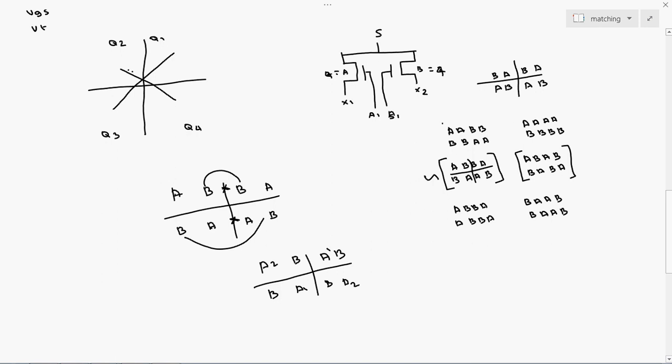See, the common center point between A and B is here, and A also here and B also here. Everything is laid out around a center point. All the transistors' on and off time, or all the transistors, are laid out around the center point of this area. In both X and Y directions, we reduce the process variation. So this is common centroid based process variation.